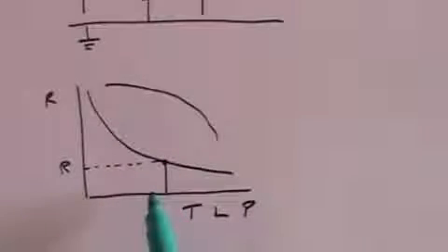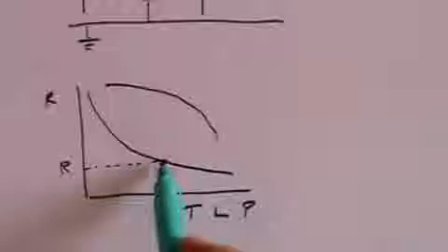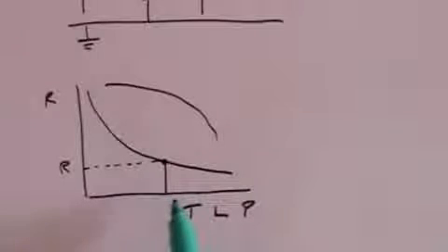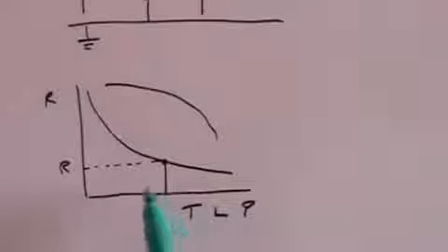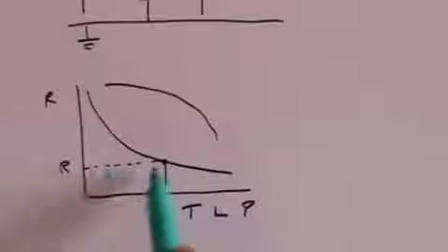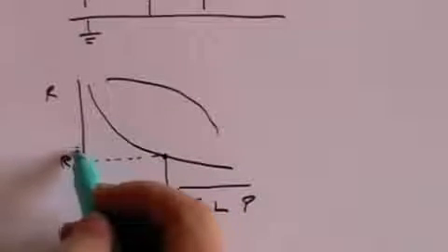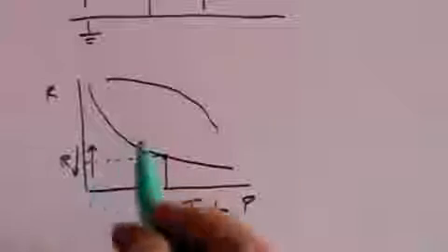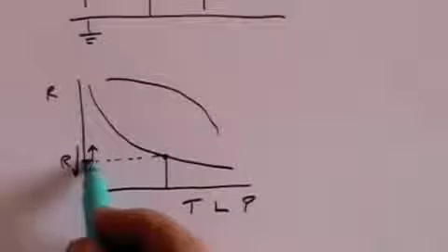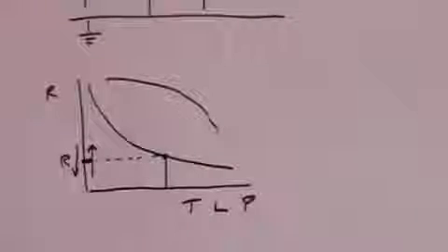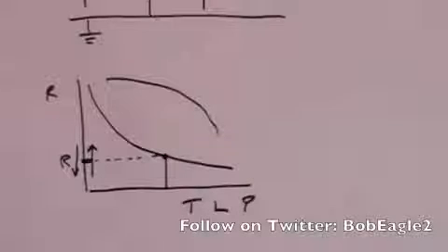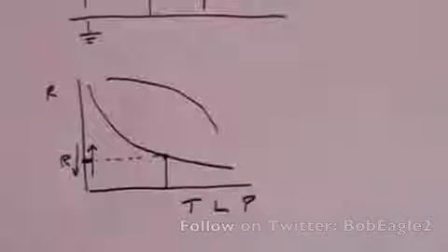So there's no straight line. You'll actually have to work out at what point you get a particular resistance that coincides with the critical temperature or lighting conditions or pressure, where you want the resistance to go through the key point. And then you have to set up your circuit such that as the resistance passes this point one way or the other, the effect is that the operational amplifier's output flips from being positive to negative or vice versa.